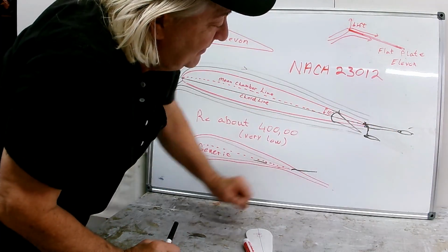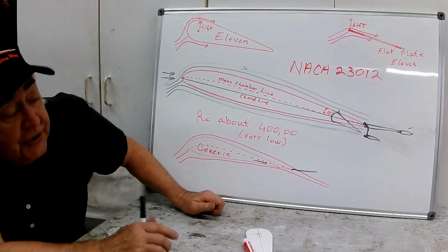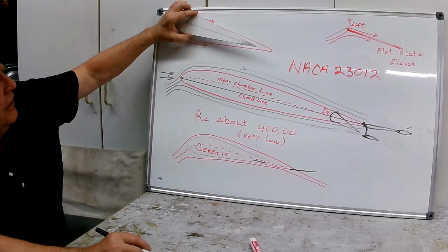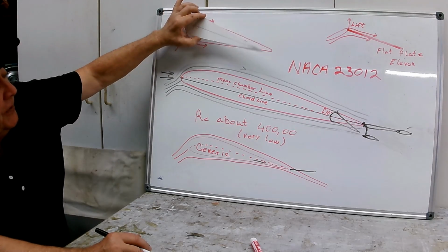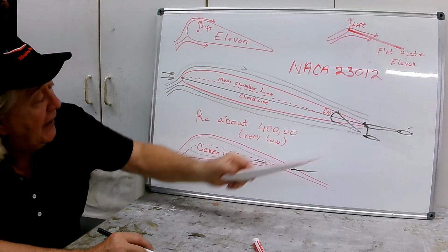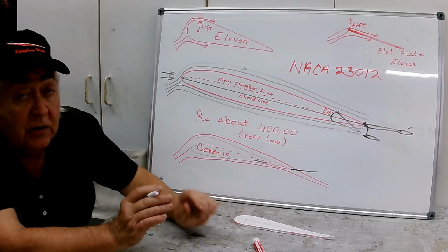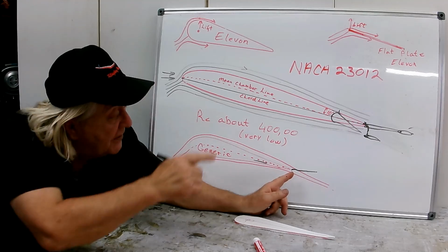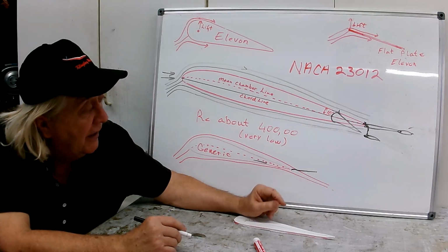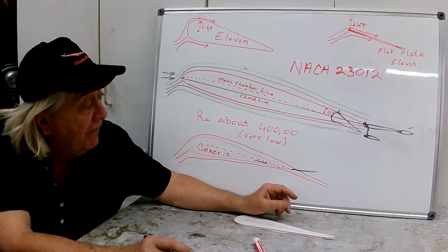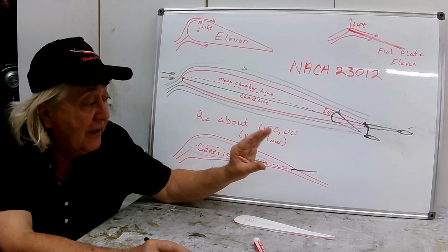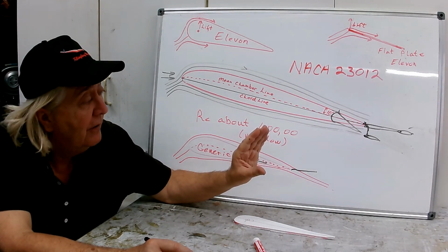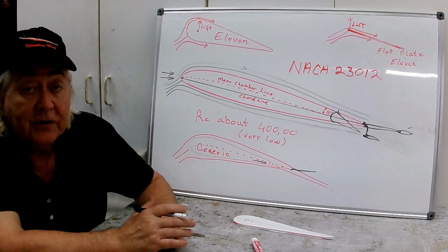So not as effective. We'd really want to reshape the potential flow field, which is what we do with regular control surfaces. That reshapes the potential flow field. The flat plate avoids the problem of the discontinuity for up to 10 degrees at the trailing edge here. So we get 10 degrees of throw available for reshaping that potential flow field, for reflexing the airfoil both up and down. And we get some control effectiveness that way.